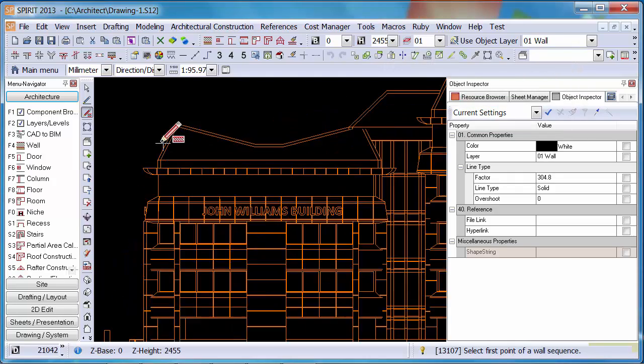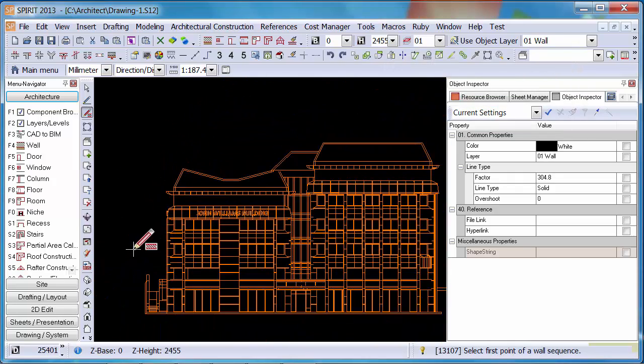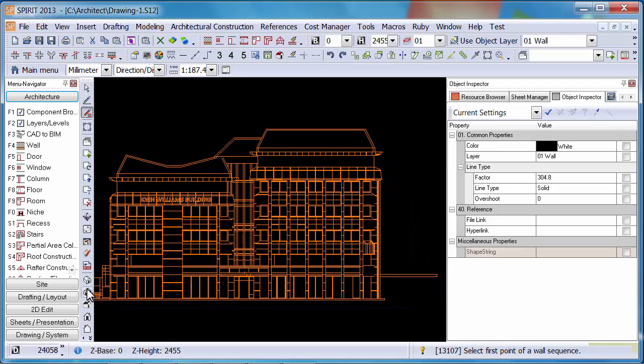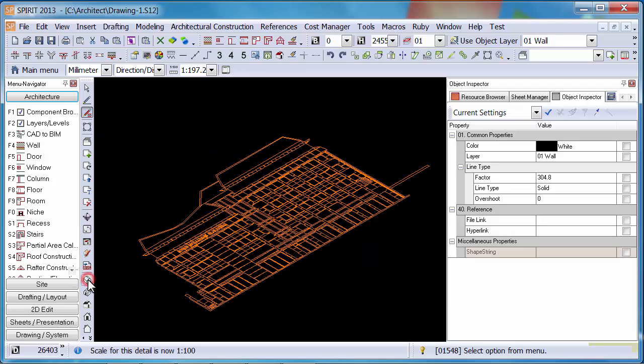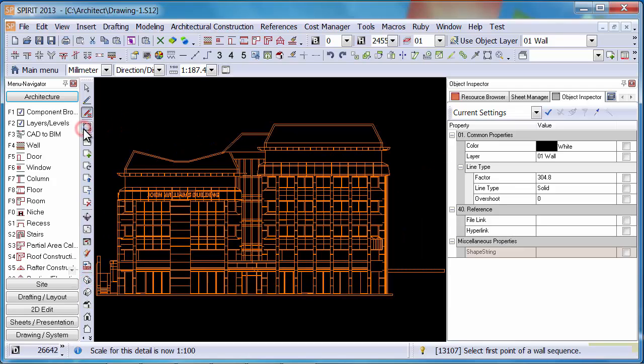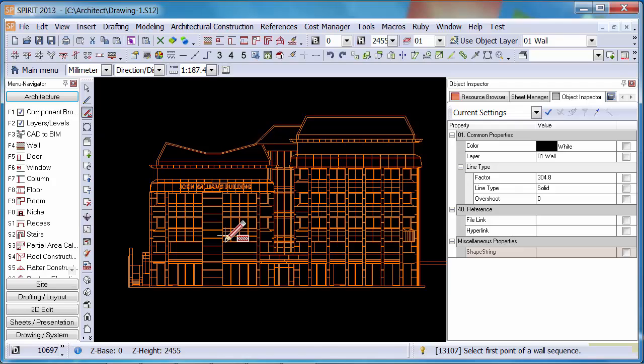Those lines have come in as 2D lines, and if we go to an orthographic view, you can see that they are just flat 2D lines. This is really handy if you're doing your conceptual design in SketchUp, and then you want to take this line work to CAD and do the construction drawings from there. It can be quite a good method.